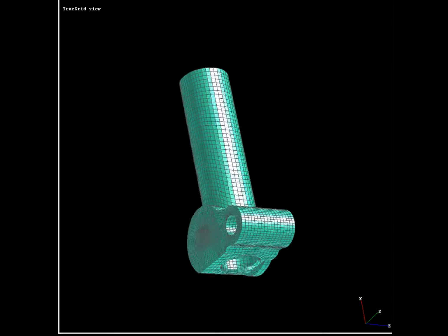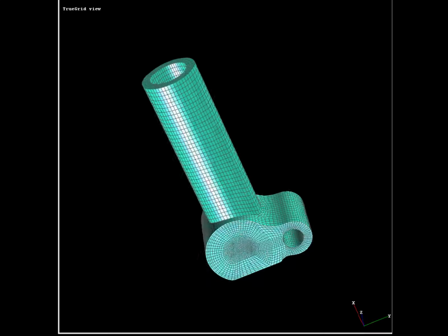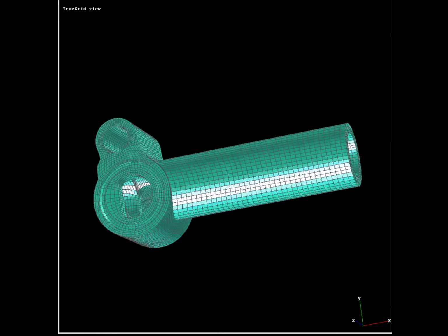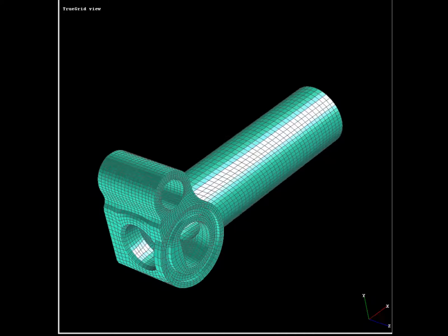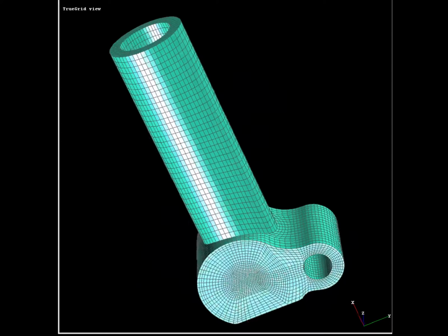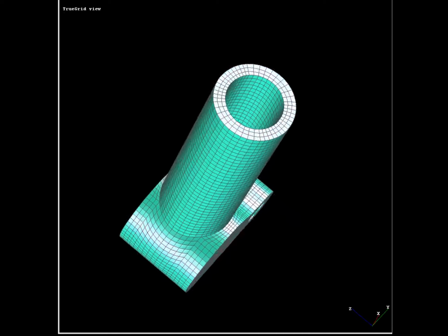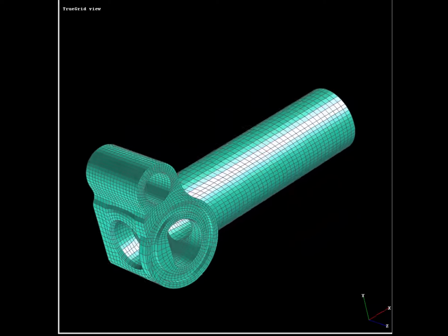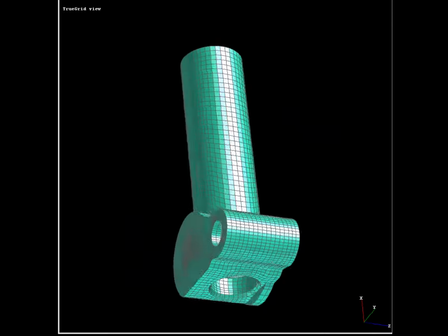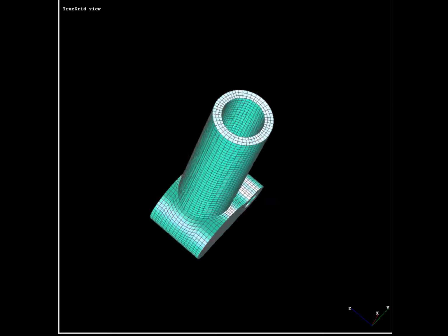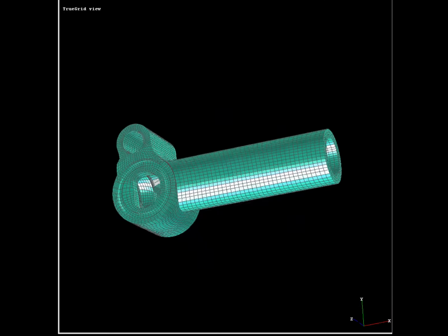In this example mesh, created using TrueGrid, we have a structural component consisting of 26,463 nodes, 21,154 hexahedral brick elements, and 91 prism brick elements. This small number of prism brick elements were needed near the overhang because some of the intersecting surfaces were tangent to each other.